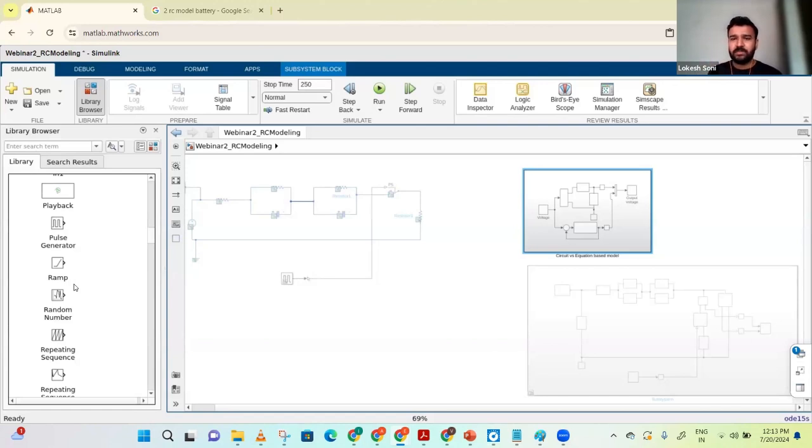Okay, so this is how you do RC modeling and how you use the RC model further. I have told that circuit level implementation is more for the understanding part, but when it comes to developing algorithms, it is mostly equation-based development, because then you open up the world of stability, the response behavior, the frequencies the system is entertaining, the frequencies it is not entertaining, or noises. All those things are analyzed better in equation form. So an RC model or any circuit is converted into differential equations or Laplace domain transfer function form, and then we do the further developments.